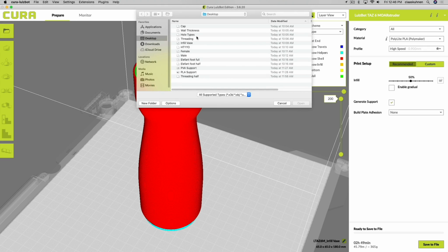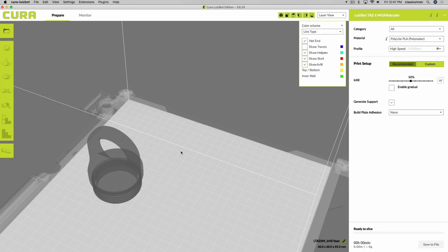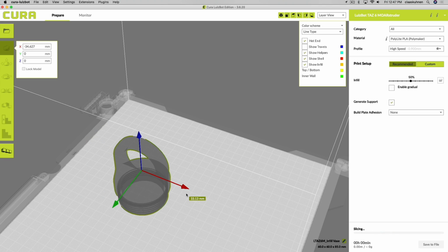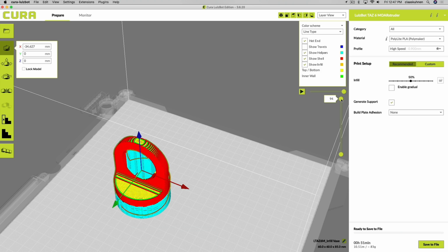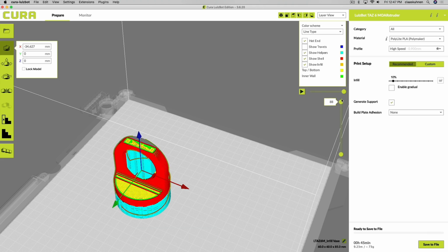Let's actually open OneCap, because also there you see the infill always at work. There we have it. If the object is very small, I don't really need a very high infill. For the vessel maybe, or if I press hard on it, I might need a little bit more infill. But with something that is rather small, I can definitely get away with a smaller set of infill, and that will be strong enough.